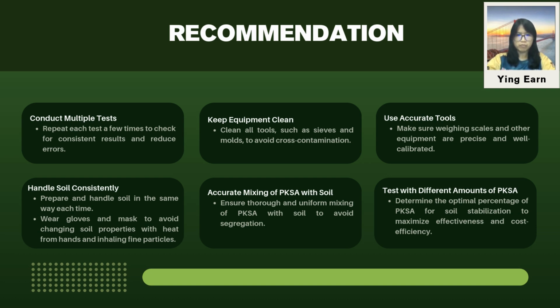This can be done by preparing and handling the soil in the same way each time. For example, we should wear gloves to avoid changing the soil properties with heat from hands, and also wear a mask to prevent inhaling fine particles.